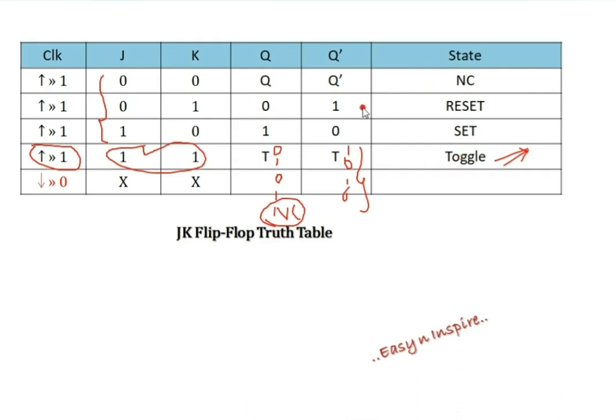Okay, this is the truth table. So here JK both are zeros, no change state. 0 1, reset pin is highlighted because it is like SR, right? So reset is highlighted, the output is reset. Set is highlighted, the output is set. See, reset, set and toggle. So toggle is activated only when JK must be 1 and the clock must be applied. So this is the truth table.